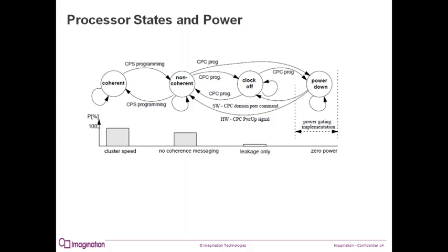A processor is in a non-coherent state when it is not part of a coherent domain. If you have more than one processing element, as is the case for a multi-threaded core, these elements will share an L1 or L2 cache coherently. But as in the case of a single processor, there is no coherent I/O or automatic coherency with uncached memory. The GIC can still be used to map interrupts and communicate through interrupts with another core. This state will use less power than the coherent state.